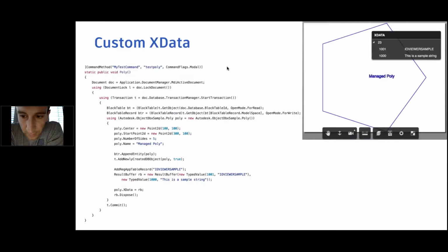Yeah, actually, Philippe, sorry, I'm going to interrupt you very quickly. Let's just give a very quick overview of what design automation is. And I can do that if you like, just in case there are people who don't know. So, just to be clear, design automation API is a web service API, so it's a headless version of AutoCAD which runs on an Autodesk server. It is not a self-hosted solution, and basically you can either create drawings or you can modify drawings, and you can put the output wherever you like.